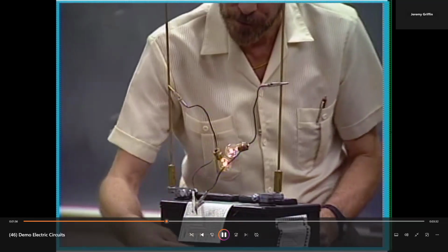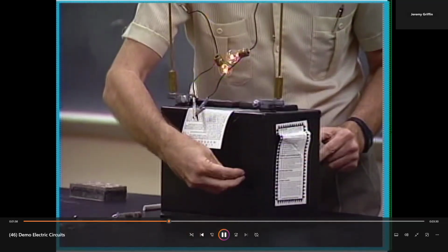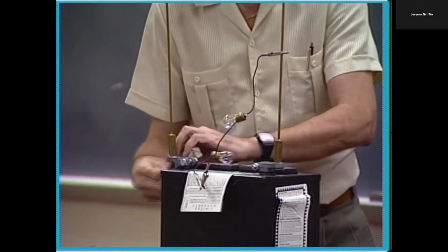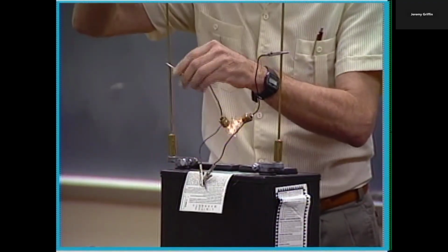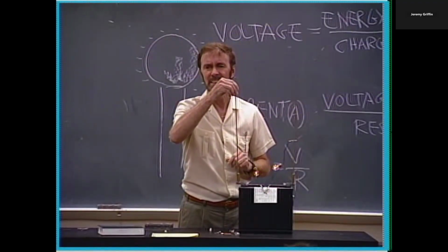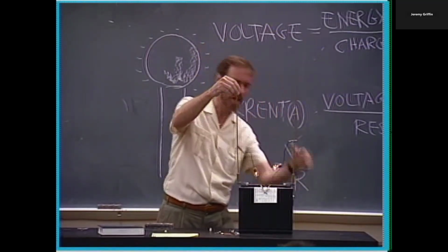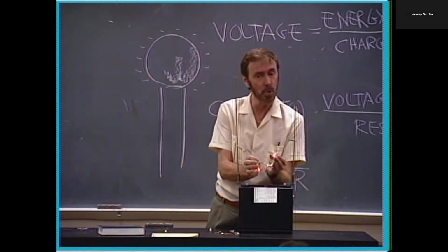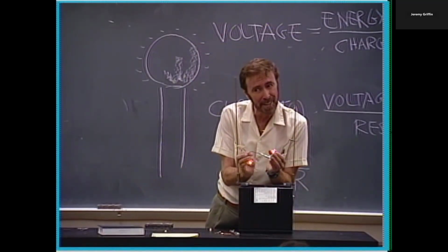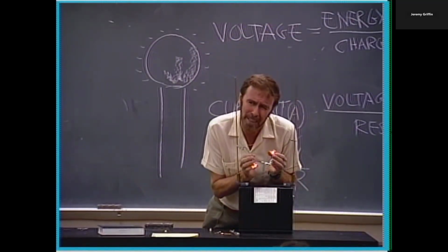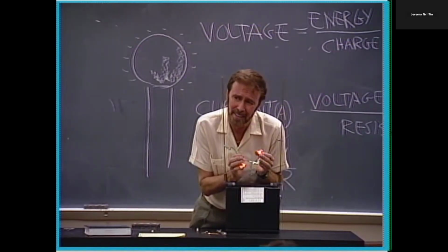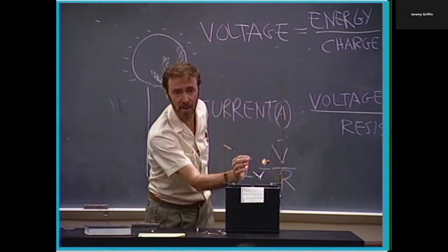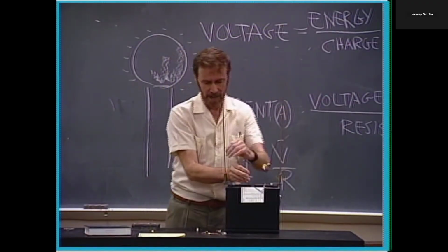And how many amperes flew through the battery? 6, 6, 6, 6, 6, 6, all the way along. How many amperes up here? None. This is not part of the circuit. My circuit's right through there. See what I'm saying? The current flowing through the circuit. And the circuit now has twice as much resistance as before. If it's got twice as much resistance, what's the current? Half as much. Do you see? Ohm's law kind of says it all. Ain't that neat?